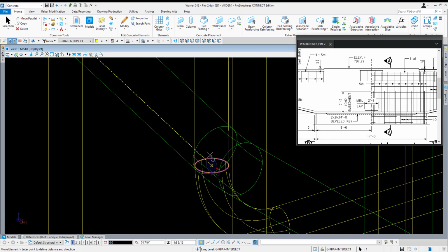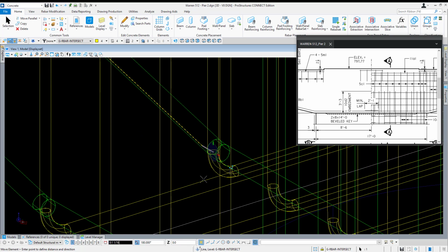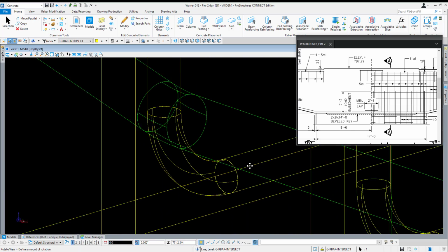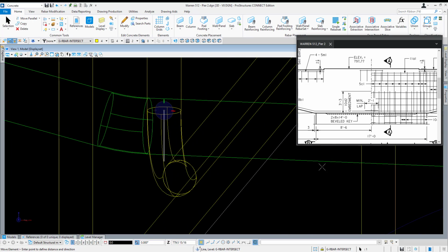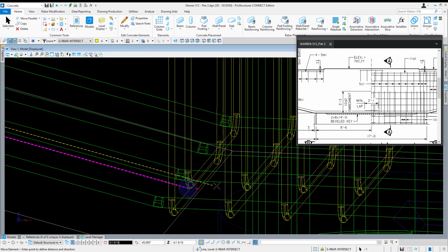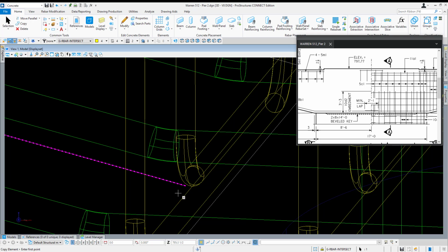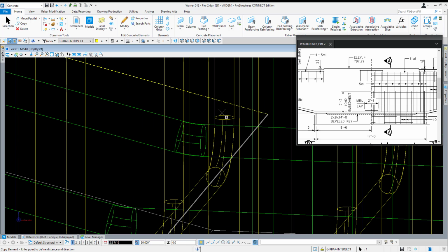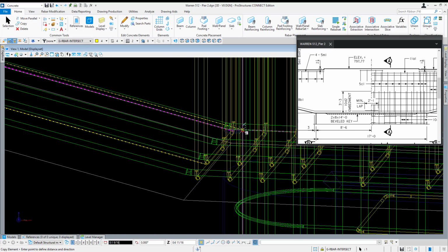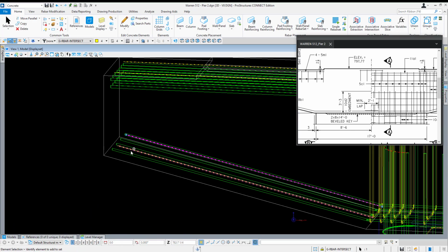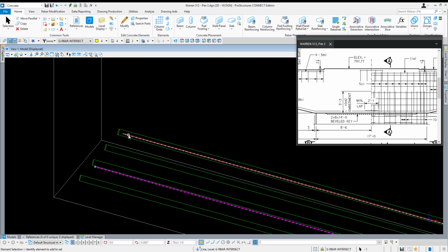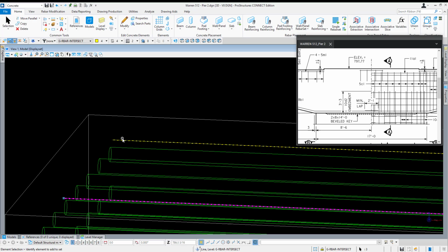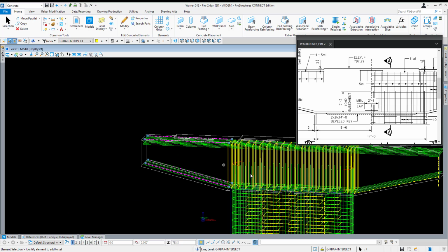I'm going to snap to there, and then smart lock downwards and place it at the center line of the bottom bar, rotate around. Always good to rotate. Don't guess, just rotate and snap to it right on. And then pull that back across to the center line here. So now I have all 4 of my guidelines placed for that set. I'm just going to highlight all 4 of them and copy them over to the other set.